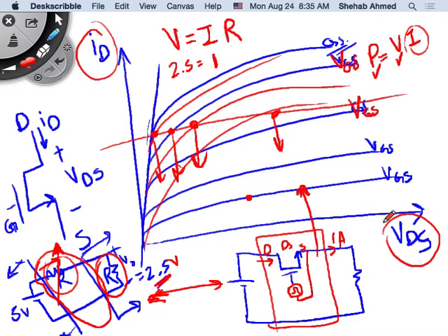Different voltage drops across the MOSFET is equivalent to what? Different voltage drops across this resistor, right? So I've done the same thing with a MOSFET in a controlled fashion, electronically. Now, instead of having somebody sit down with a potentiometer and change this resistor value, I can maybe program that in a microcomputer to change the value of the drain-to-source voltage, for example. Maybe there needs to be a circuit along that takes care of that as well. But you can do that with a MOSFET.